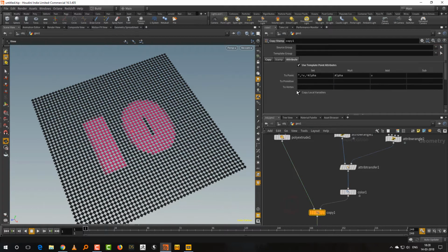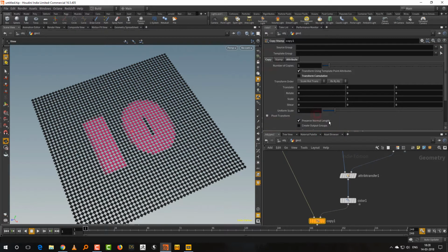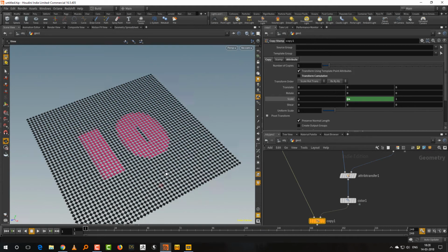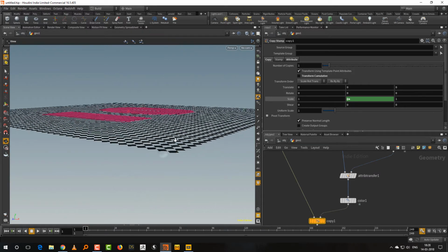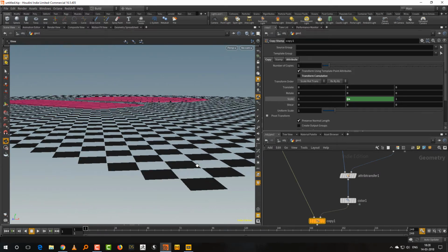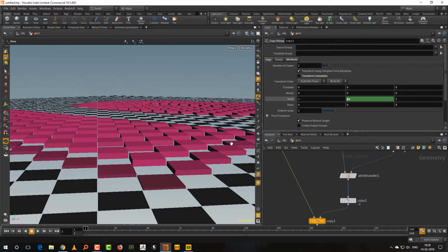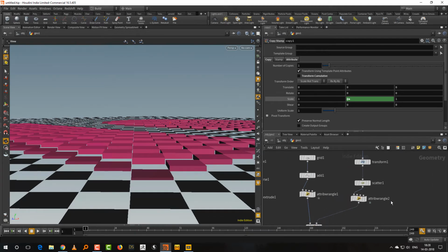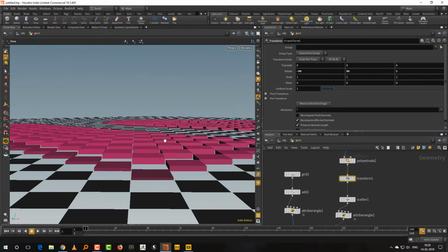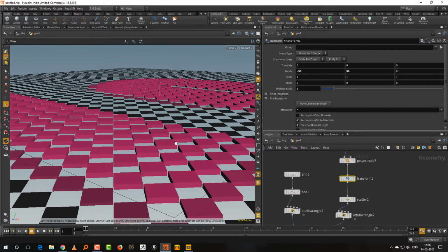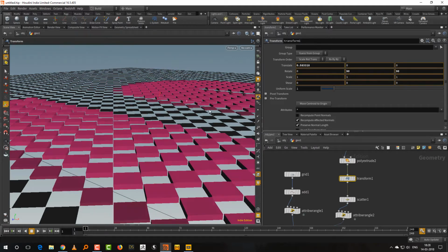So you come in here, and if I just come to the Z axis and I type @A and press enter, now something has happened. You'll notice that these became completely flat because this value is 0, and wherever we are transferring from A, these are at 1. We can move this around, and you'll see that it is transferring values. There you go.